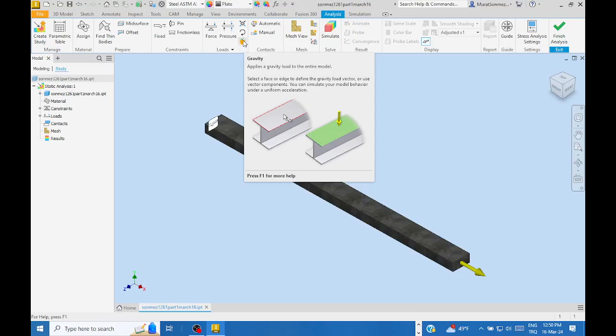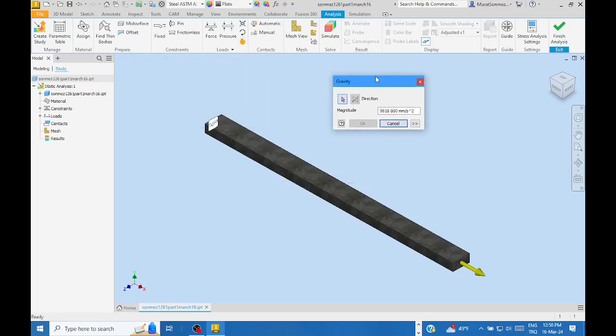If you click on this, then yes, Inventor automatically considers that the object is close to the surface of the Earth at sea level. You know, at that level, the gravitational acceleration is 9.81 meter per second squared. And then if you indicate a surface, an existing surface, it is to say Earth is over here or over there. But in this example, it is out of consideration because weight is negligible relative to the order of magnitude of the load.